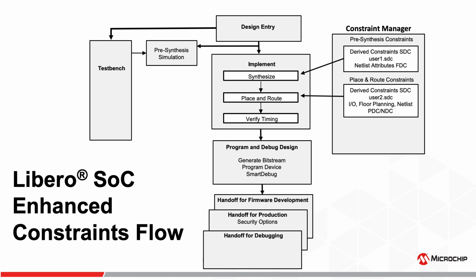PDC is nothing but floor plan constraints. So you can lock the design placements using these PDC constraints. IO constraints, as you know, are FPGA IO constraints. We will provide the FPGA pin names for your designs. At the verify timing, you provide derived constraints, which is a .sdc file.